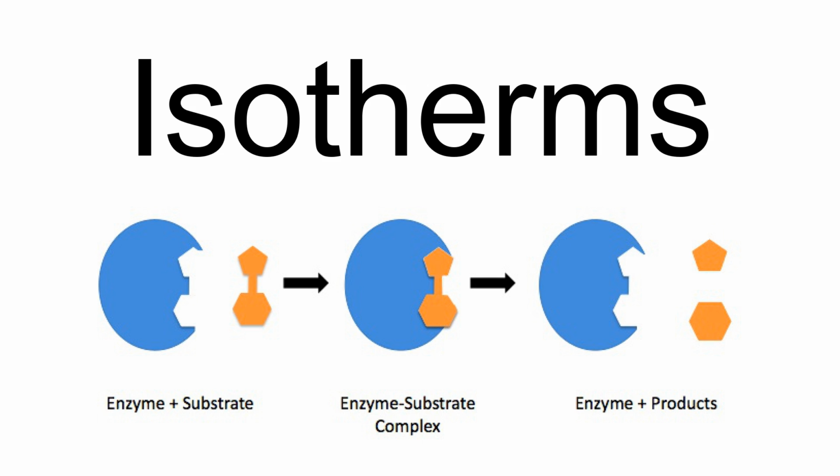V_p is the partial molar volume of protein. w_a is the negative of the Gibbs free energy of adsorption per unit area, and C_e is the equilibrium protein concentration. This equation has been applied to a laboratory setting of protein adsorption at temperatures higher than 50 degrees Celsius from a model solution of protein in water. It is especially useful for modeling protein fouling in milk processing.